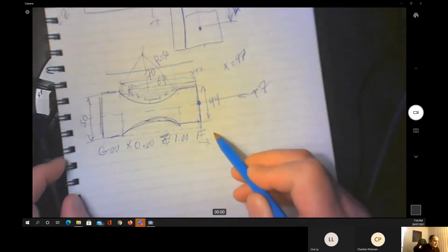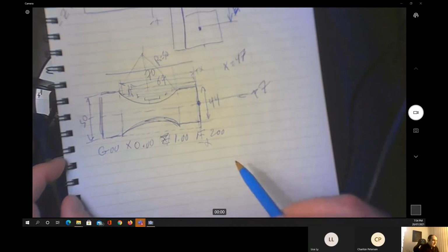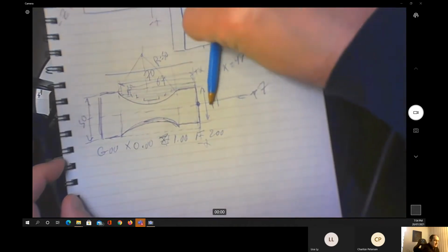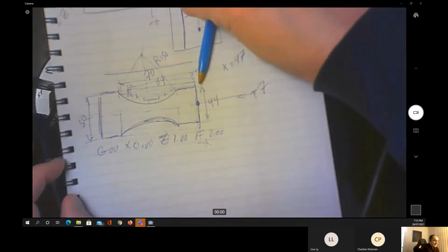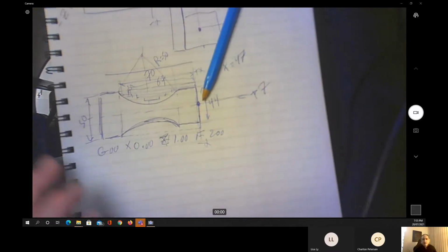The feed rate, let's say, is going to be 200 millimeter per revolution. Now, what I'm doing is I just brought the cutting tool to here. Is that correct to do the face cutting? When you do the face cutting, are you going to do it from the end to the middle or from the middle to the end?